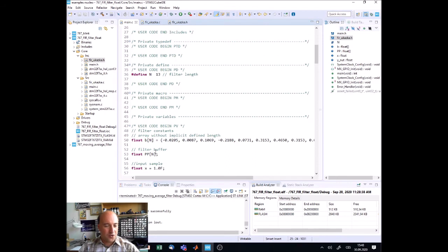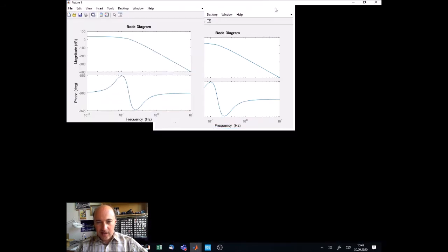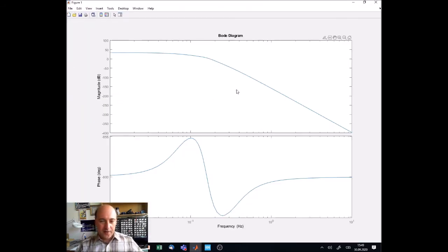And then what I've done is that here I have included my H file, and here I have some definition of signals. So I have chosen that the filter length, so the number of coefficients, is 13. This basically allows you to tune your frequency response. Basically, what is happening if you are changing the length of the filter is that you are changing how good the filter is, how good is it able to filter out the low and high frequencies.